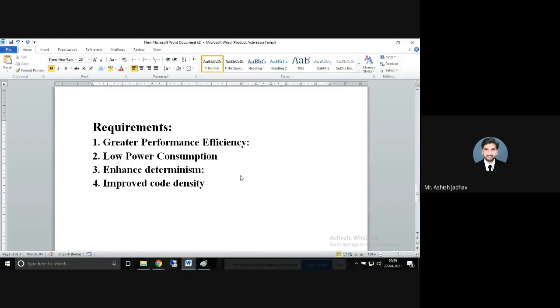In short, whenever you require to complete a critical task, you can do it by using 32-bit instructions. And whenever you require high code density, means what? The things should happen in a minimum number of cycles. In that case, you can execute 16-bit instructions. So this is what is called improved code density. This will ensure that code will fit in even the smallest memory footprint.